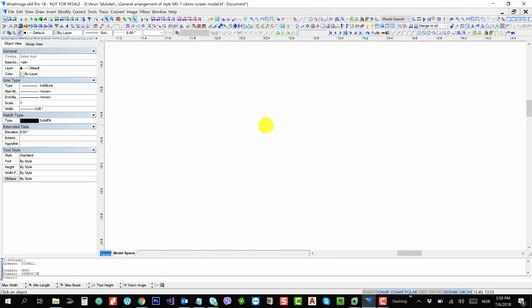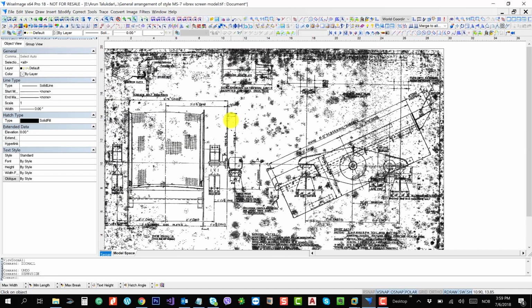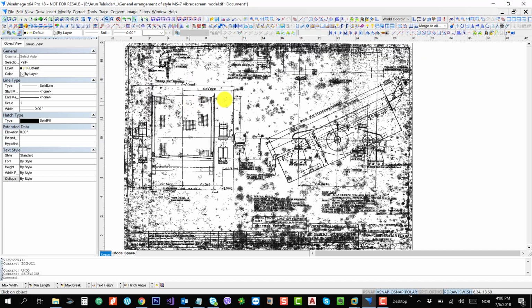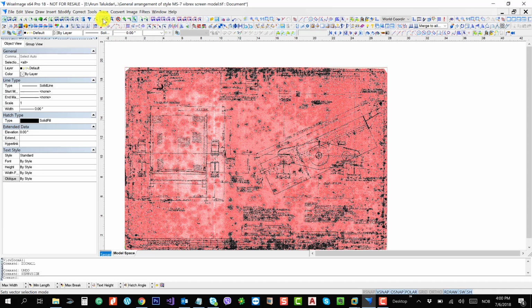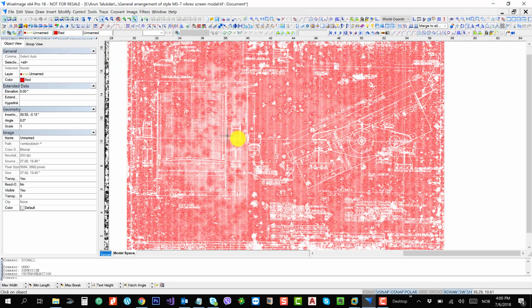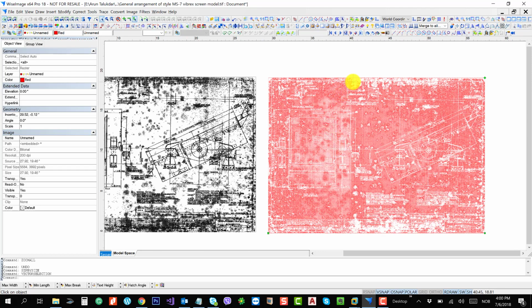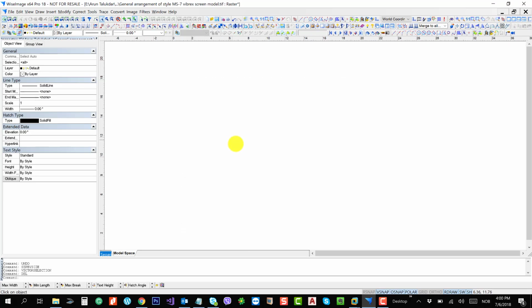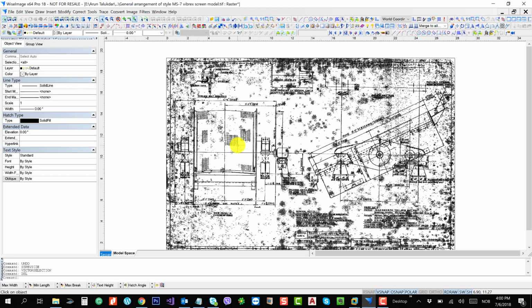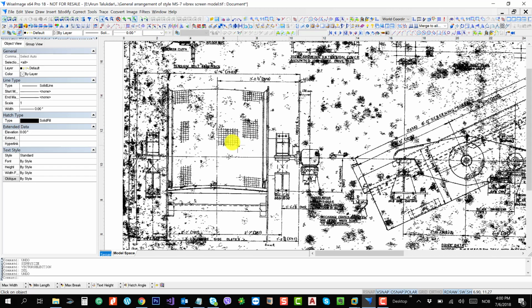What it does is mark out all the noise in the background of the image with a specified color. Now you can see the background is marked out, most of the unwanted objects. So drawing entities are safe, and you can drag the noise out from the drawing. So these are all noise, you can cross-check, and if you are okay, then you can delete. So you can save the drawing entities, and at the same time you can remove the unwanted objects from the drawing. That covers all the enhancement.